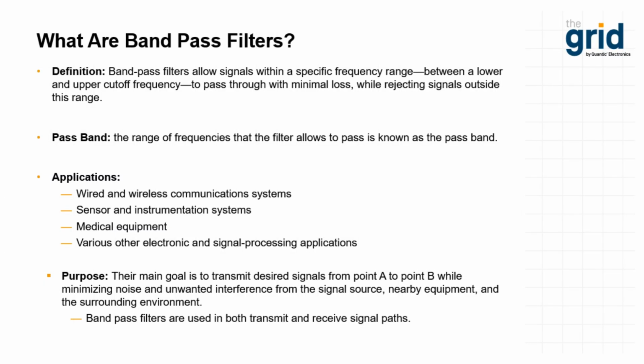All right. So as I said, bandpass filters will allow certain frequency bands to pass while rejecting others. And a typical application for something like that would be in a communication system where you are trying to transmit signals out on an antenna, and the amplifier that you're using to boost the power up might have some harmonic distortion or intermodulation distortion in the signal.